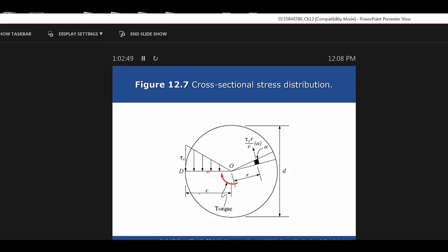So for the hollow shaft now, it's a little bit different. Note, and some people did this on the temperature thing, you tried to do like 0.030 over each one of those temperatures, and that wasn't quite right. You couldn't do that. Same thing on this. If you want to find that polar moment of inertia, you can't just subtract the outside diameter from the inside diameter and raise that to the fourth.